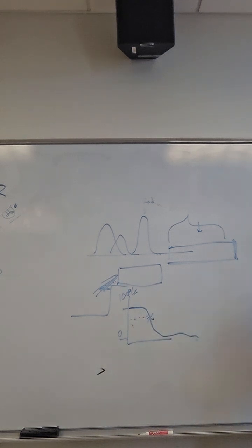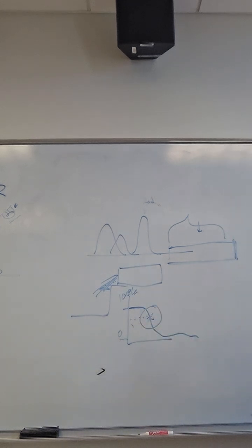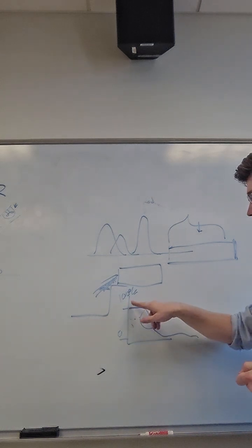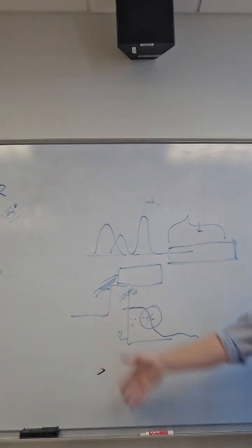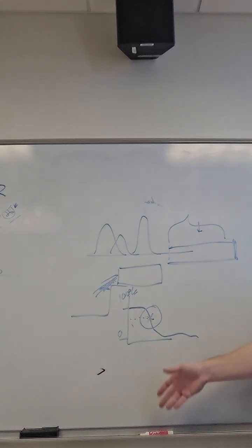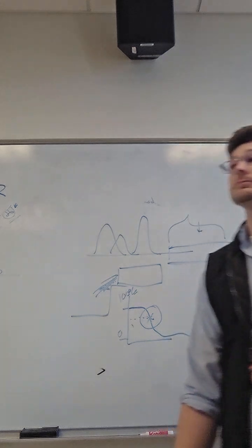So that typically is like the extent of the complexity of your PLC program. All you'll really worry about or care about is, okay, in this analog signal, how do I establish this threshold to do the thing that I want to do when it needs to do it? Okay, and that it does that reliably and that it doesn't mess up and it's accurate and all that good stuff. Okay, so that's IR sensing.